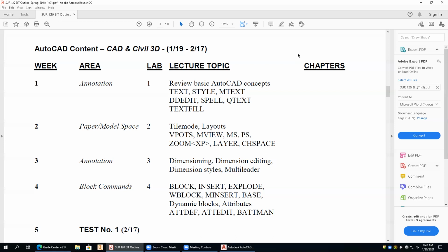Okay. So each one of those is a potential justification point that you can use to bring your text in with. Now you won't use all of them. There's some I've never used, but sometimes I want to line stuff up. I use that one a lot. I use that one. I use that one. So these are good to have. When you create the piece of text, you can only come in with one of them. But that can be moved after the fact. So if you create a piece of text that's left justified and you want it right justified, you can go into the properties of the text and change it. So you have all those abilities.